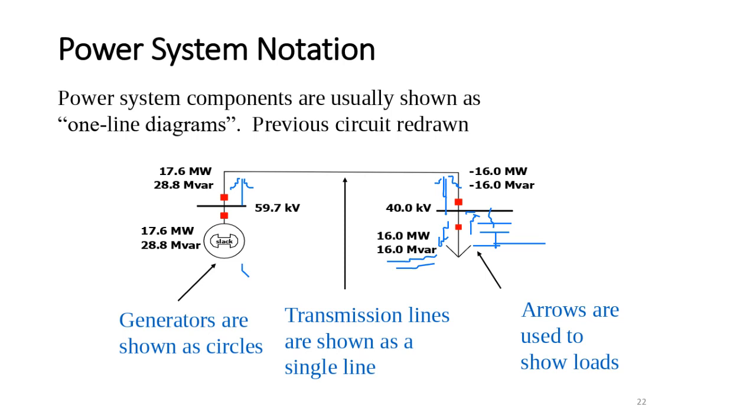In the industry they have heavy motors, large motors. Therefore, they put capacitors here, so the load absorbs the reactive power from this capacitor. But if this is too much compared to the load, where will the reactive power flow?